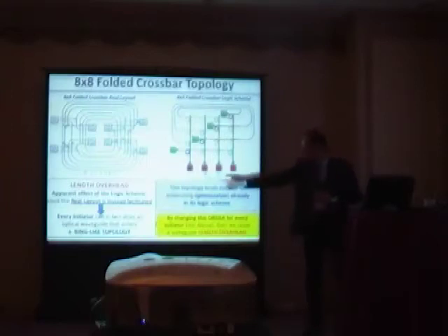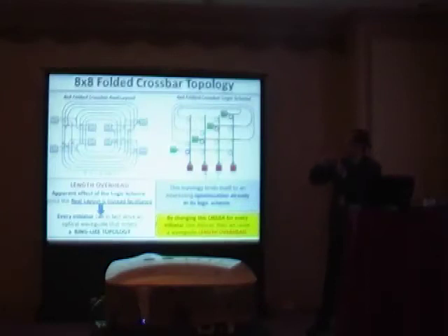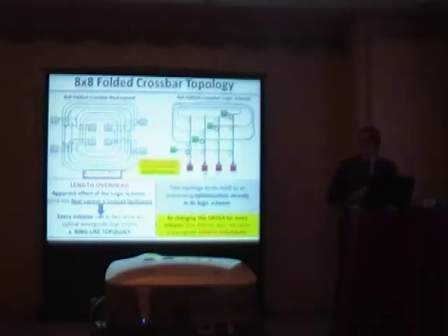In fact, every initiator can drive an optical wavelength that enters a ring-like topology, like this. This is an example of the path. Notice that the most important contribution in insertion loss is the crossing loss. Even here we have 7 distinct wavelengths which are needed to deliver all global connectivity.